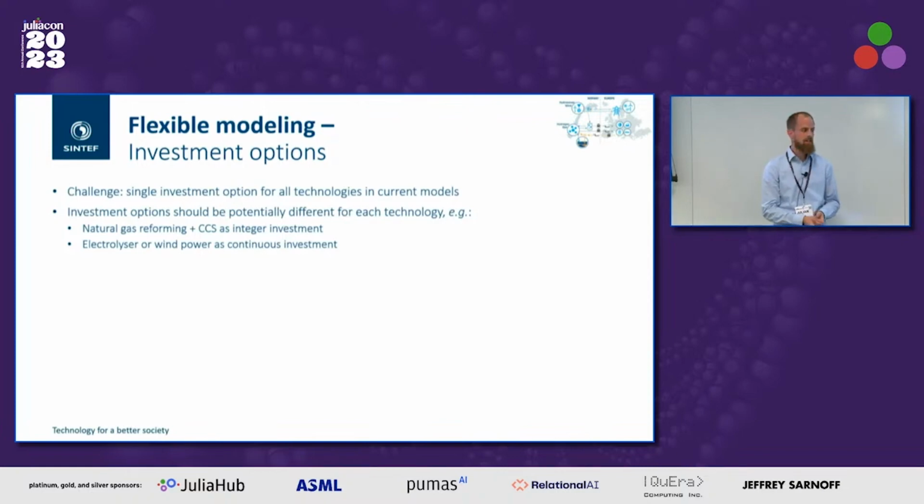On the other hand, electrolyzers, excluding balance of plant, purely electrolyzer stacks, have way less economy of scale. It's essentially in this repetition. So if you reached 100 megawatt, they're pretty much multiples of 100 megawatt. Wind power, largest one, is currently in the range of 18 megawatts. So if you're talking about gigawatt installations, you can treat it as continuous.